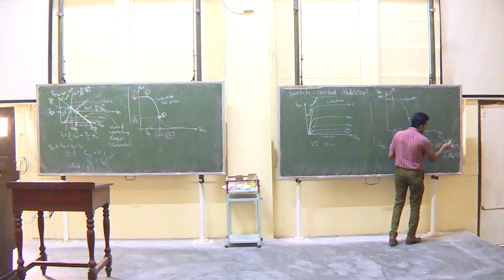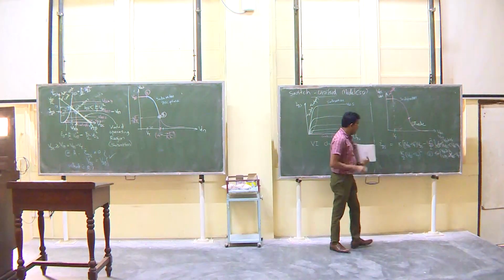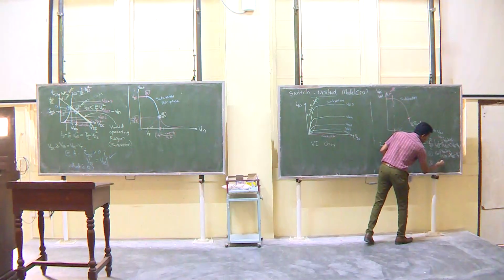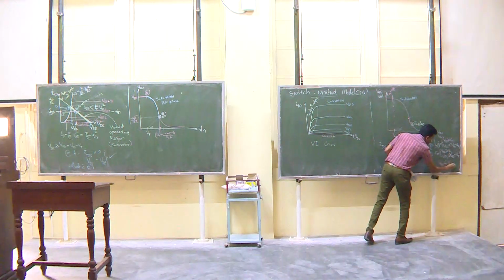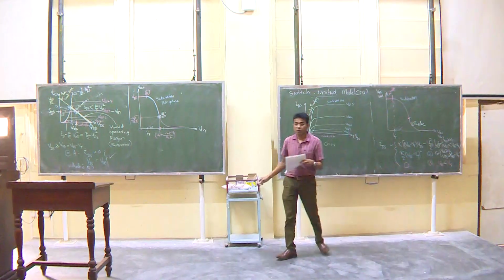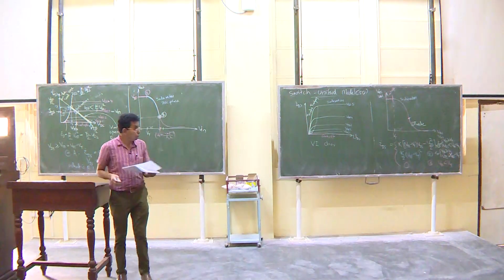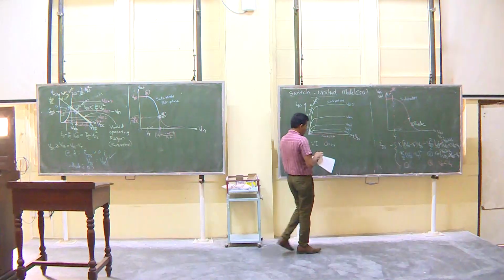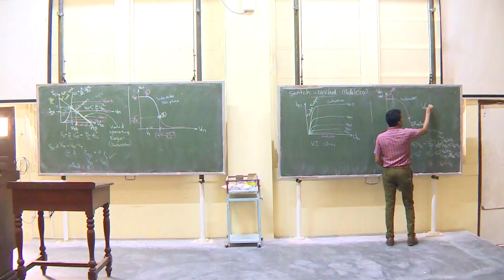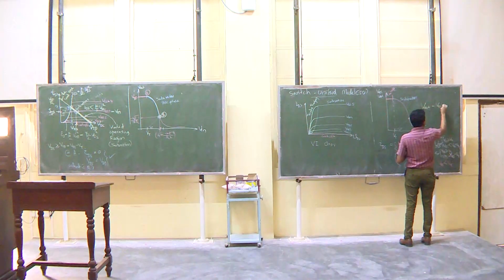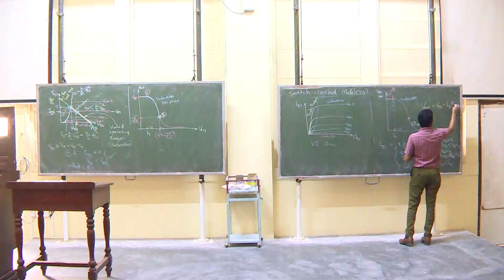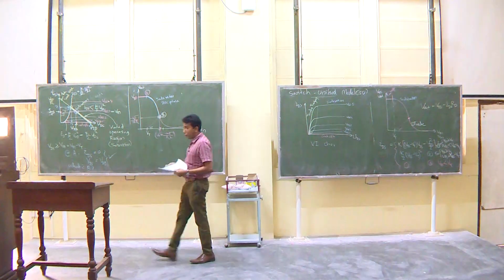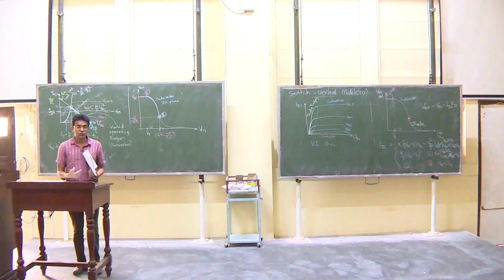So, both these things together, and for the cutoff it will be 0. That is your full model, right. If you know the IDS, we can find out the Vout easily, because it is equal to VDD minus ID times R. Right. So, therefore, you can find both the output current as well as output voltage.